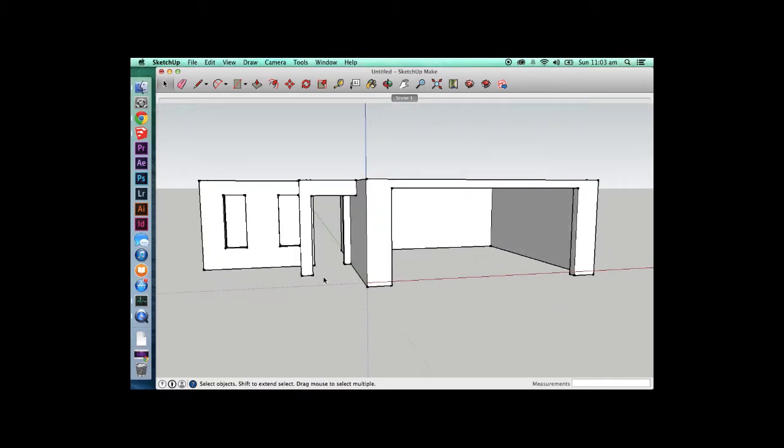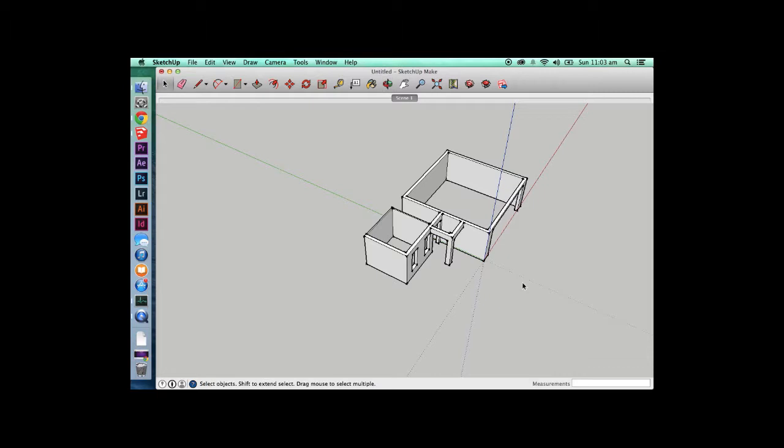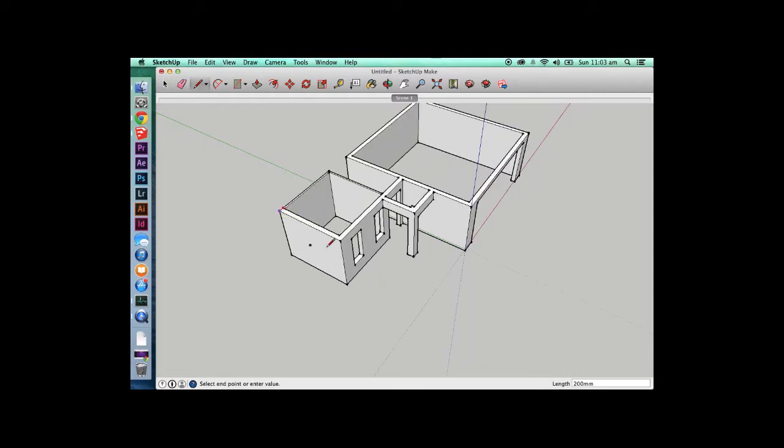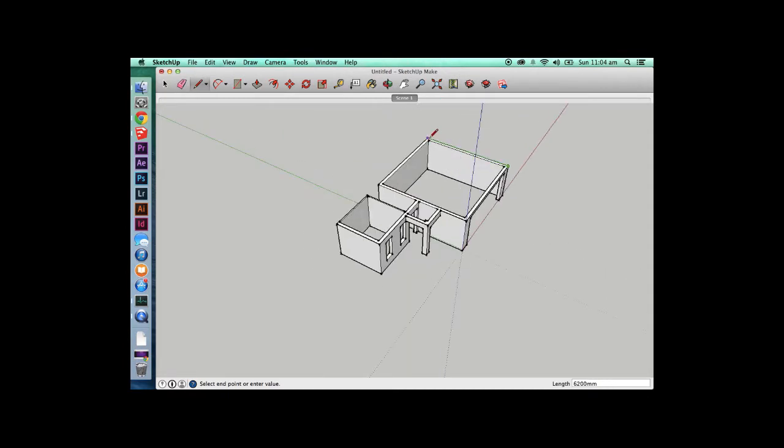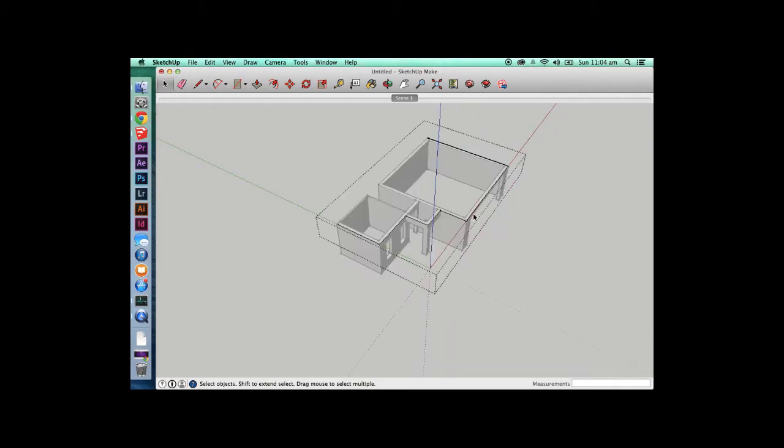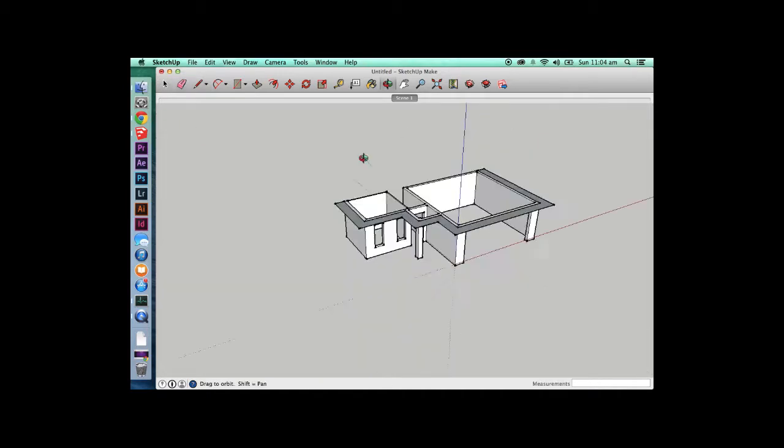Now obviously these are just the walls. I'm going to start adding the roof now into this front area. Now, where I am in Australia, our eaves are usually 600 millimeters projected from the wall. So now this is my wall line. I grab the offset tool, come out 600. There's where our eaves are going to be. That's going to be our eave line.